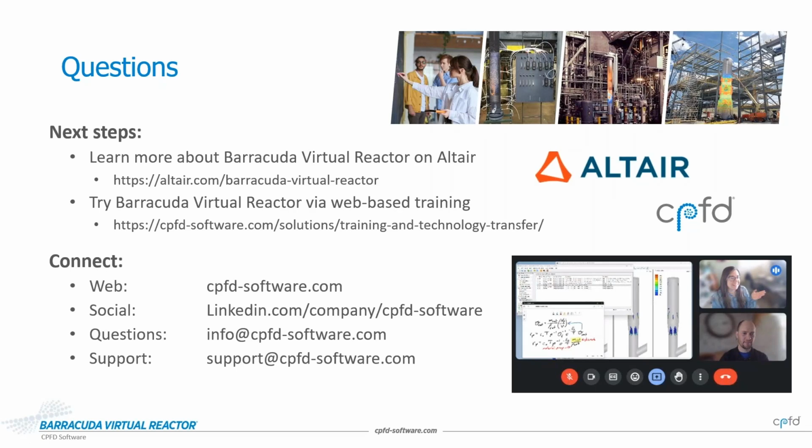If we do have people who, within a single Barracuda model, have put vessel 1 connected to vessel 2, sometimes with a standpipe or a transfer line, then depending on the number of cells and the number of particles that you can handle with your computer, you could certainly put multiple vessels in series within a single Barracuda model.